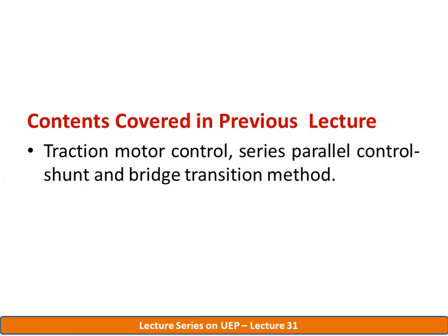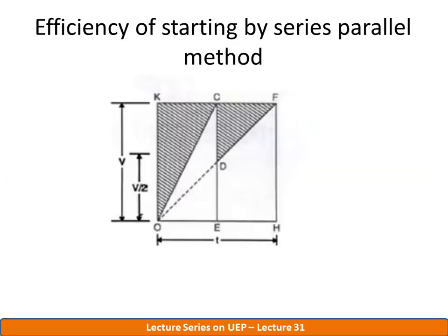We studied the series parallel control with the help of a graph. We also find the efficiency for the starting, the efficiency of starting by the series parallel method. Here it is clearly shown that the shaded portion is the voltage drop across the starter. When supply is applied, the white portion is the back EMF.